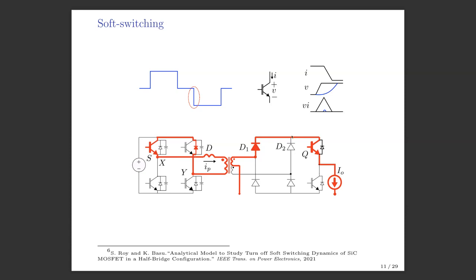So this is one phase of our converter, that we have just seen. And I told you by controlling this H bridge, we are applying a quasi-square waveform, like this blue waveform here, across this bus, whose duty cycle we are changing sinusoidally. And let us look at the situation when we were applying zero voltage across this XY terminal, or across this transformer, and we are here. And we are going to study the transition to a negative voltage.